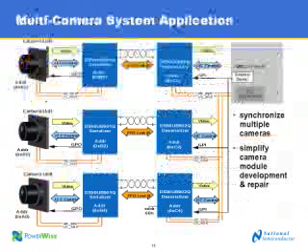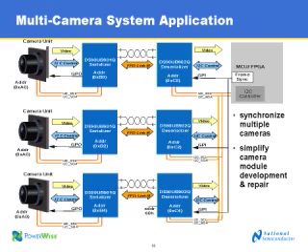In addition, this whole address remapping we're talking about, this is where it comes into play. In this case, you have 3 camera units, and their address is all the same. What we're showing here is A0 as the address. Well, this gets remapped. Each deserializer is told, I have a camera with address A0 mapped here, but I'm going to call it something different. And the user assigns a new and unique address within the deserializer's registers to tell it and the microcontroller, hey, when you want to talk to the camera, use this new pseudonym, right? He's got another name now.